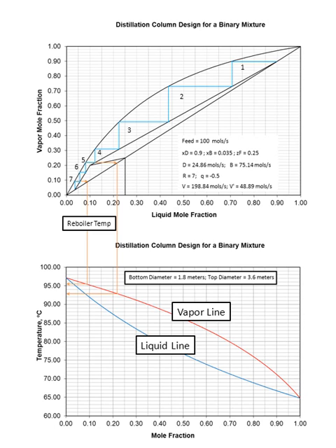or 95.5 degrees C. Likewise, our feed stage can be projected over, and we'll find that the temperature at the feed stage is 93 degrees C. So we can easily find what the temperature is on any particular stage by projecting down.